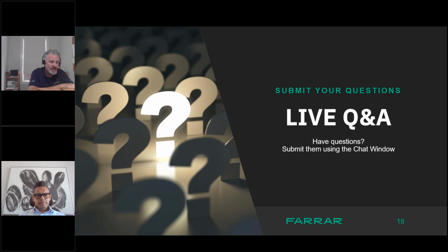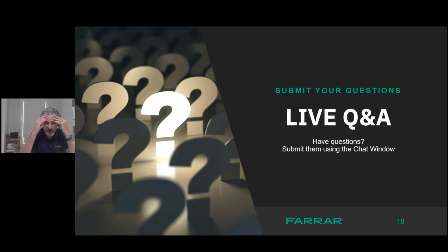That's an excellent question. So what you're going to be looking at in regards to this is you're not going to look from a uniformity aspect on a horizontal plane or a vertical plane. What you're going to want to do is look at it from a volumetric, where everything is going to be located. So we would look at it from the design aspect and how you want to create that volumetric uniformity. Say it's a 2 to 8 degrees C chamber and you have it at 5 degrees C plus or minus 2. We have to maintain that plus or minus 2 throughout the structure.